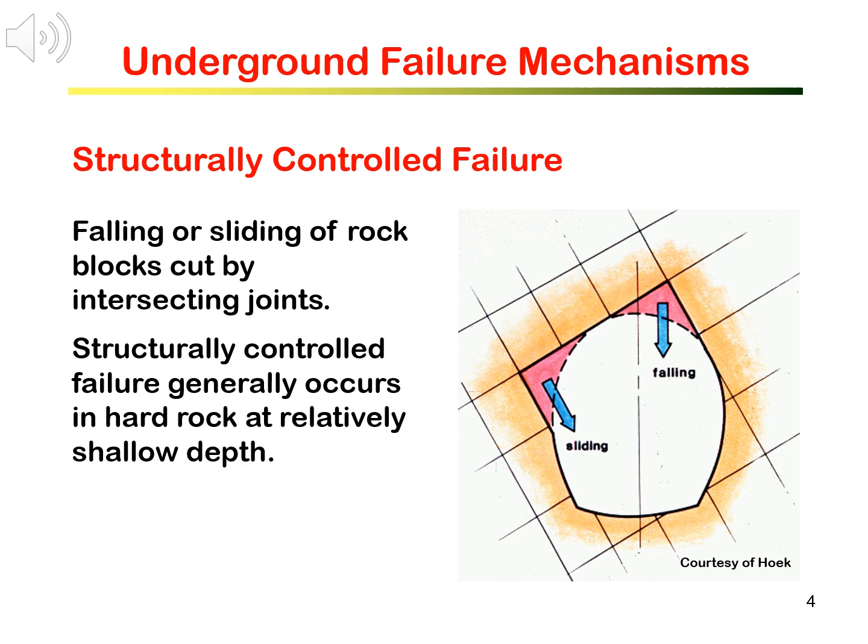For underground excavations in generally competent and good solid rocks at shallow and moderate depths, as for most of the tunnels and caverns, failure of surrounding rock mass around the tunnel is by falling or sliding of rock blocks and wedges that are formed by intersecting joints, as illustrated by the drawing here.